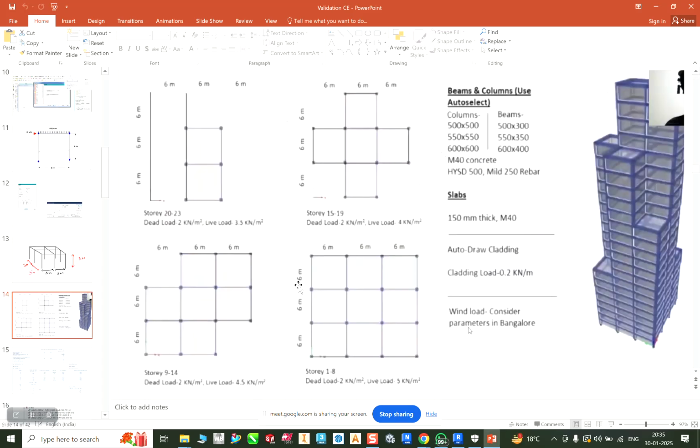Yeah, so you can take this example over here. We have a building, a 1 to 8 story building. Right now we are only going to work up to the first floor, that is level 1 and level 2. Here we can see we have 3 spans of 6 meters, and 6 meter spans in the Y direction also. And the default height is 3 meters. So how do we create this grid?